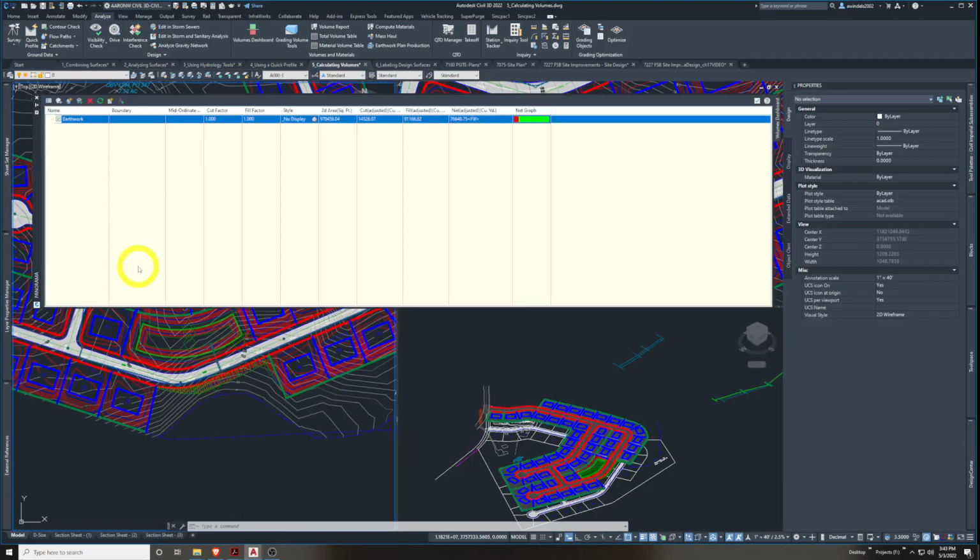So now we're going to make a bounded volume surface to a more specific area. Let's stay in our Volumes Dashboard, click our one volume surface. Let's go to this icon here, Add Bounded Volume, to click here to add a bounded smaller area.